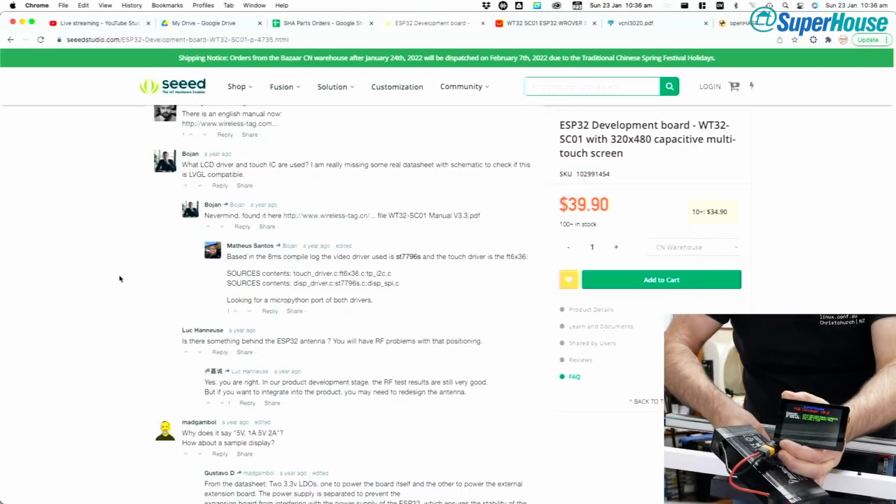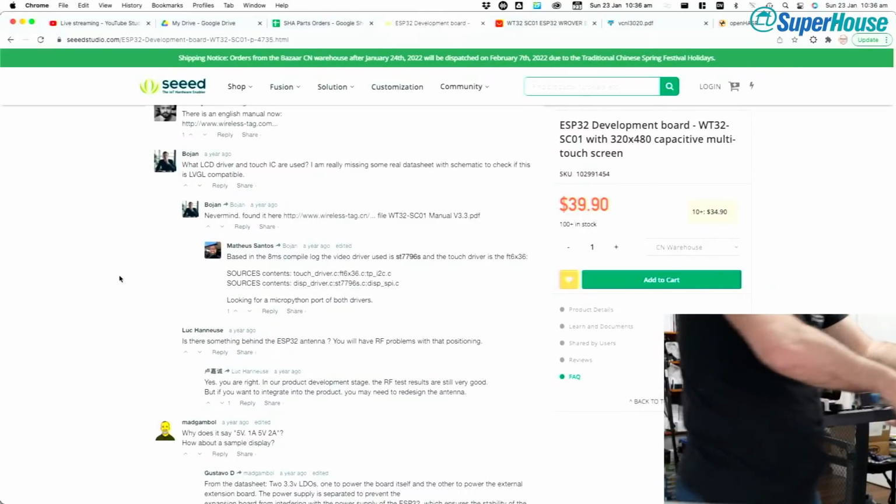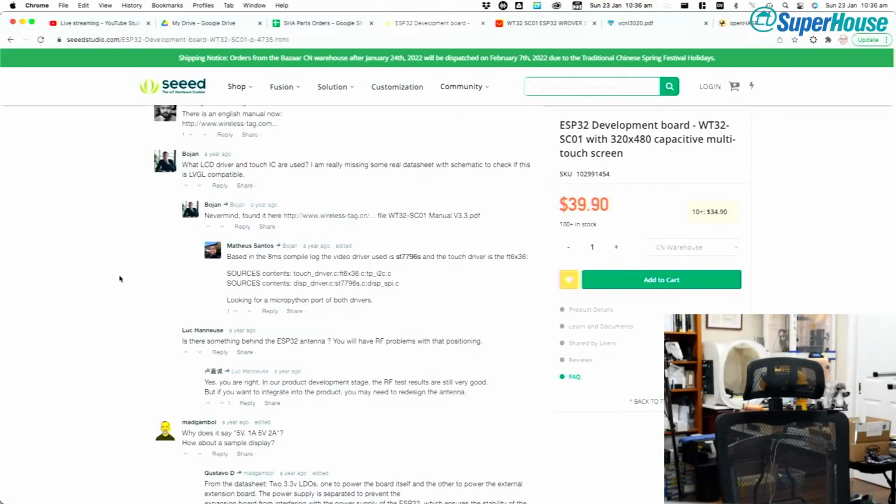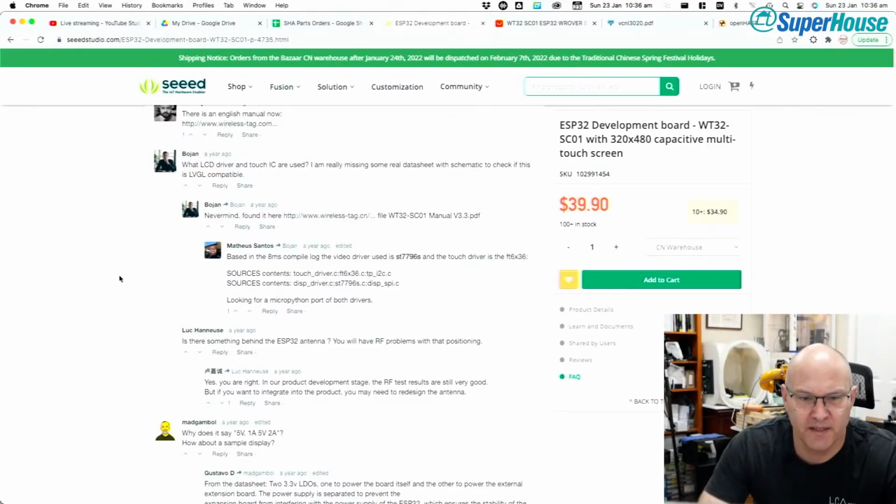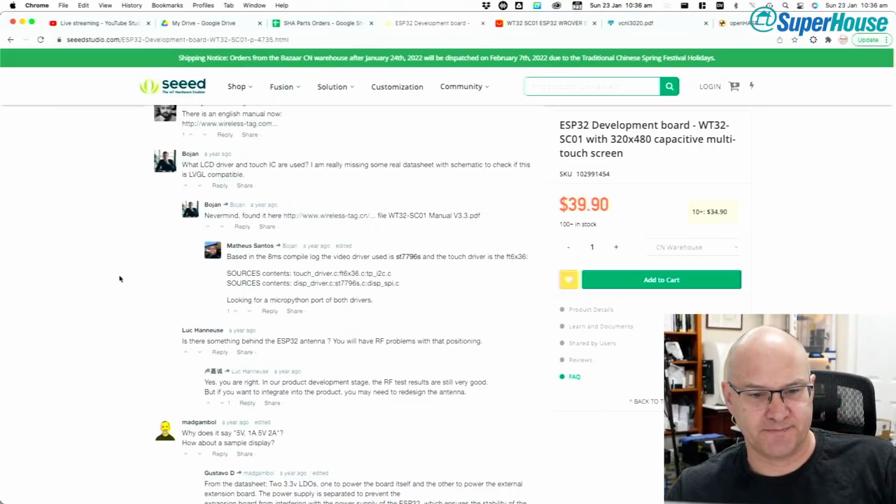And it's also reading the touchscreen, but it's not doing anything at the moment. If I connected the serial console to it, it would be reporting the XY coordinates of touches in the serial console. Yes, it has an ESP32 on it.